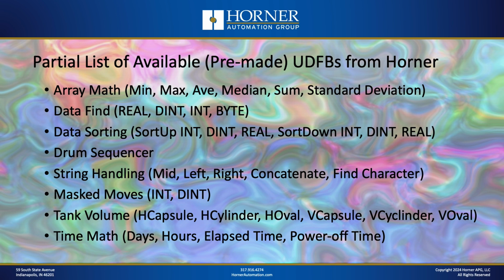We're also going to show you and talk about a drum sequencer user-defined function block. We're going to show you how you can expand your string handling capability if you've got ASCII type applications that you need to deal with. We'll talk about what some of those are. We'll talk about something that's called a masked move, which you may not be familiar with, but it can be really useful. And then we have some UDFBs for calculating tank volume and some really interesting ones for doing time math. So let's go ahead and kind of go through these with a little bit of detail. The original videos for each of these UDFBs has all the detail you could ever need. So we're going to reference those videos and allow you to go look those up if you're looking for additional details. All right, here we go.